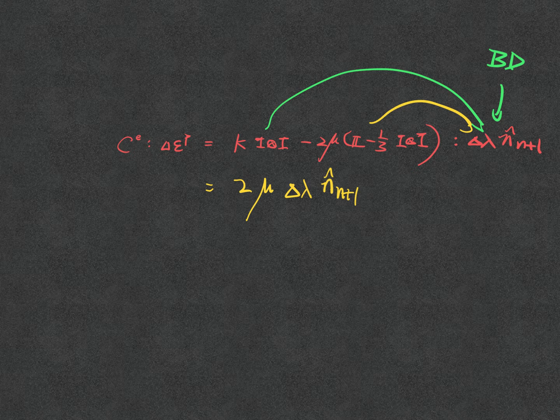It makes sense: whatever bulk modulus you have, it doesn't matter, because your plastic deformation only depends on the deviatoric part. Anything coming from the bulk modulus is taken out because the elasticity is isotropic also. There's no coupling, so shear and volume are completely separate in the isotropic elasticity part.